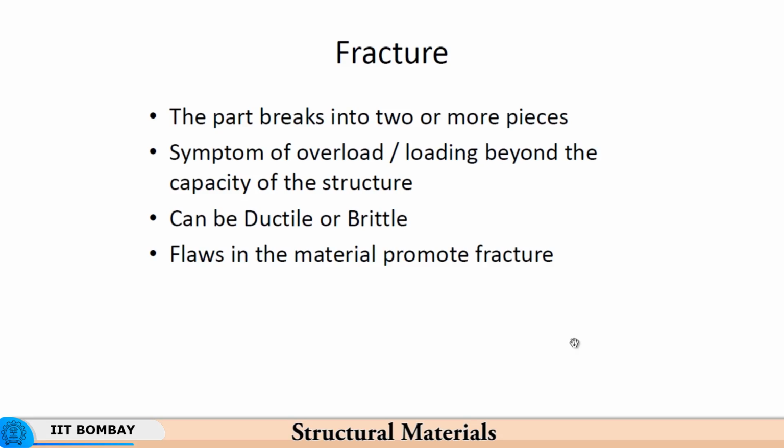People do not wait until the defect has propagated and led to a major flaw, which would in turn endanger fracture of that critical part. So this is something one has to be aware of, that flaws always exist in the material, and most often they determine the life of the component. In nuclear reactor type of applications, the flaws get generated internally during the service period, because of nuclear irradiation. So after a certain number of days, even if the part is apparently usable, it has to be replaced.